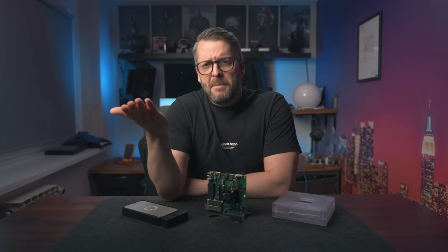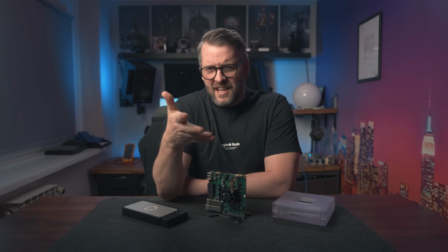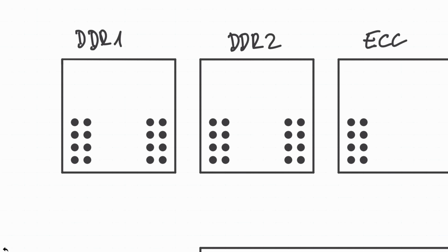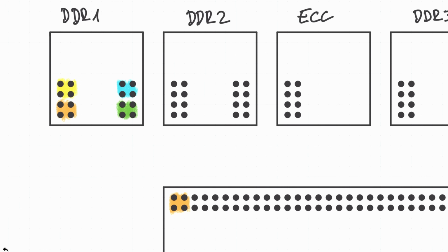To not overcomplicate things, think of bit swizzling like this. You have 16 data lines that connect the CPU to the first DDR chip, for example. Now group all of them into 4 nibbles, so bits 0 to 3 are a nibble, 4 to 7 are a nibble, and so on. What the standard allows you to do then is to connect the pins within each nibble however it makes the most sense and is the easiest from a hardware design perspective to the corresponding nibble on the CPU.